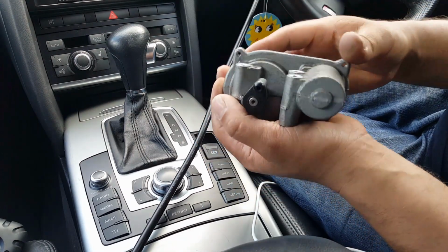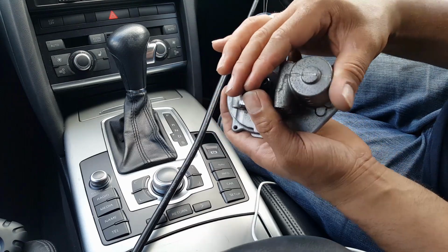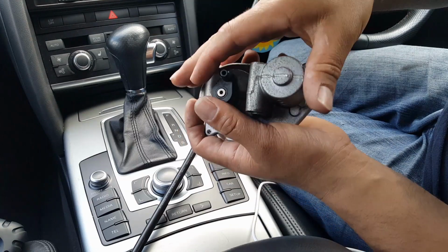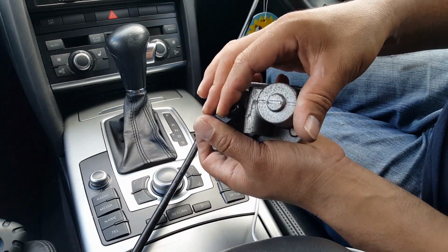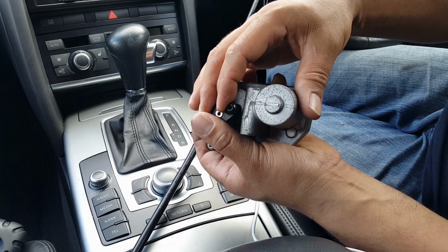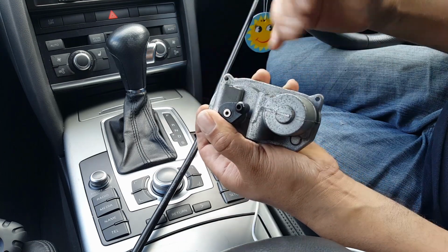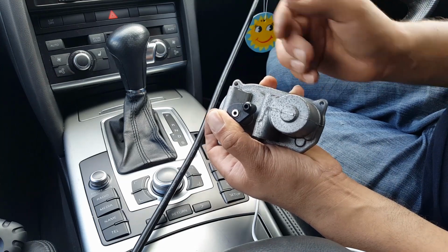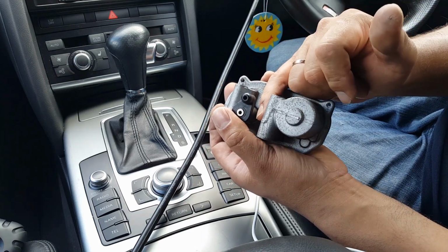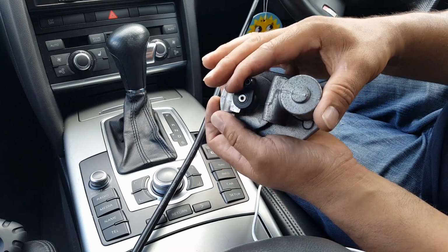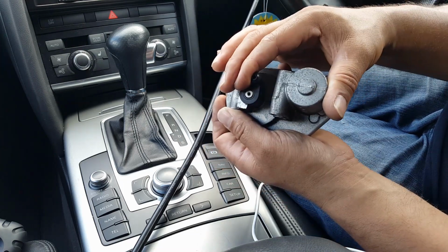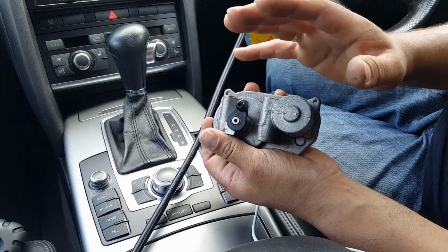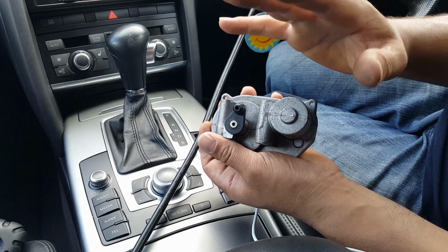So what I've done is I've measured, so let's say that could go all the way down to there. Obviously this is with the linkage in place, all the way down. Then I left this coming a little bit back, and I put a screwdriver underneath. The missus came here, turned ignition off, that went up, the screwdriver was still in place, turned ignition on, that went down, hit the screwdriver, and came back straight away, and it was firm. So I knew the ECU took that as that point, as the lower limit reached.